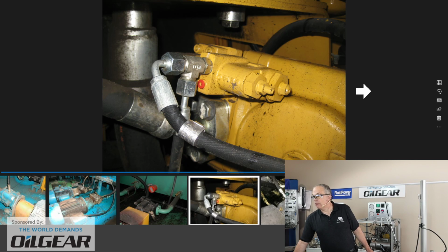Okay, what do we got here? Mobile equipment, some Caterpillar equipment. I believe this one's from a grader. And again, we see the two controllers sticking outside of the pump body. Pressure compensator being the larger one, or pressure cutoff. We're going to talk about that. That's limiting a maximum system pressure, watching out for that very tippy top pressure. Yes, there may be a relief valve set another 300 psi, perhaps higher, but that's for just in case. This pressure compensator will be the main top pressure regulator.